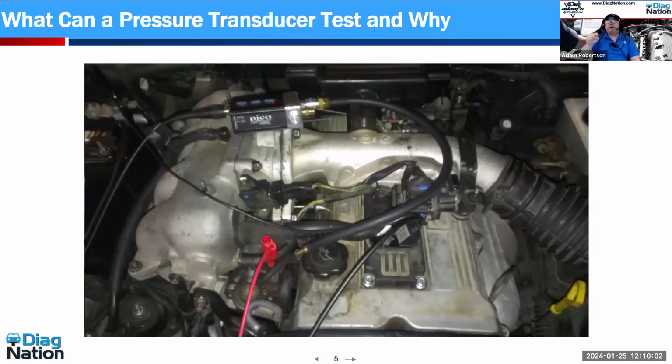This is great. And some of you that practice with your lab scope might not have even thought about this test. Once again, I'm using the same Kia here because we're going to use this as our case study. But I have my absolute pressure transducer, my WPS 500X. If you follow the hose, you will see that I have it plugged into the fuel pressure regulator vacuum port. So what I've done is I pulled the vacuum hose off of the fuel pressure regulator, and my pressure transducer is physically plugged into that port. I want you to think about this. What would I be measuring with that crazy kind of setup with my pressure transducer?